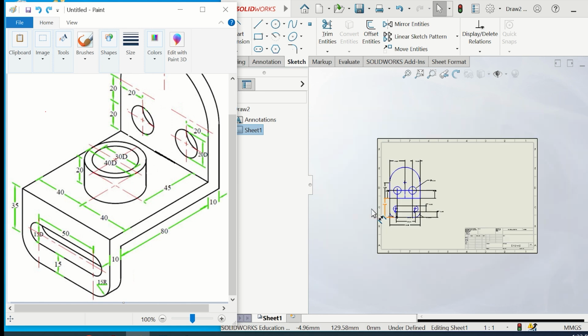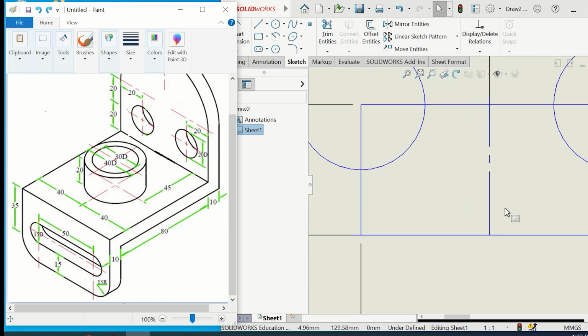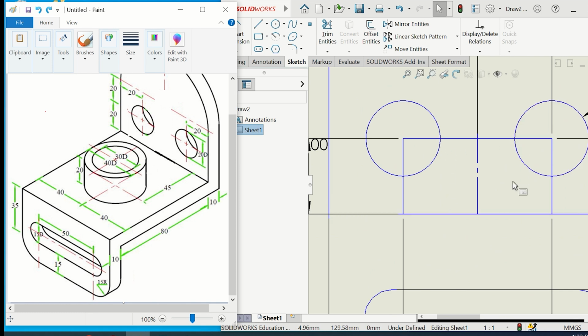So it's simply another rectangle here, like this, as I said, of 30 units by 20 units. Now, this rectangle that I want to draw will actually only appear as two vertical lines. And why is that? Because here I already have a visible line, a complete and continuous line, which will come above the hidden line. And therefore here I just have to draw two lines.